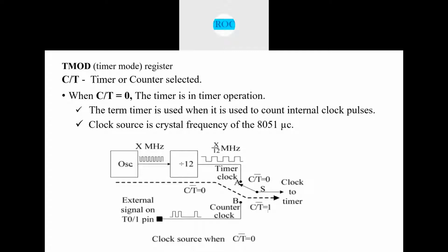We also studied the importance of the C/T bit, the timer or counter selection. When I say timer mode or counter mode, the main difference is whether the clock signal is internal to the 8051 or external to the 8051 microcontroller.